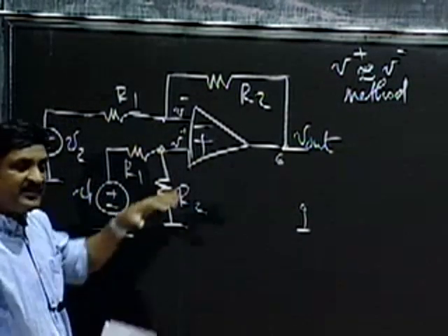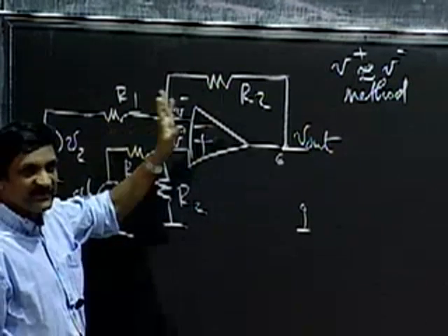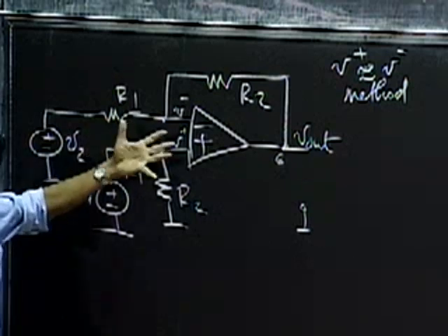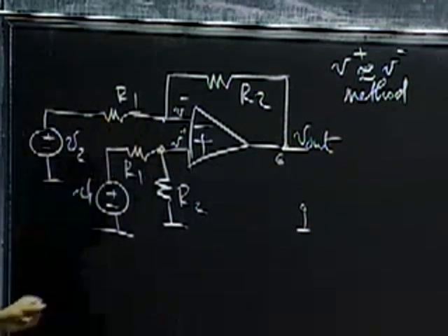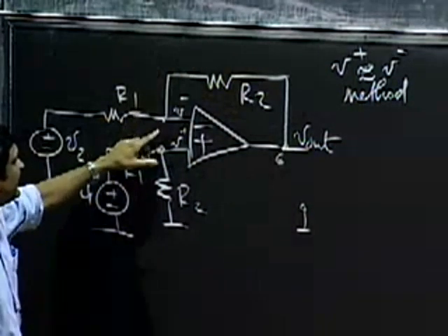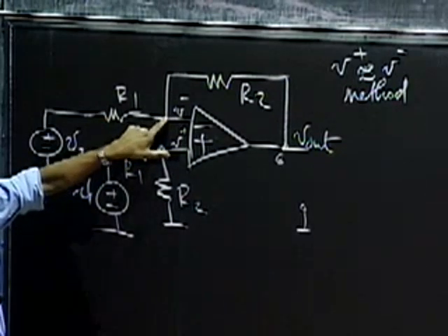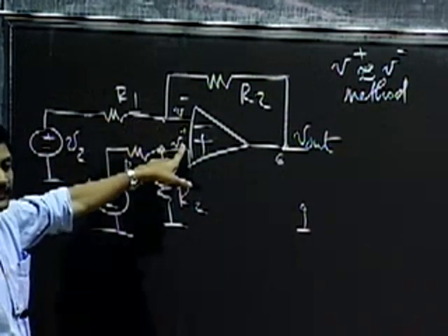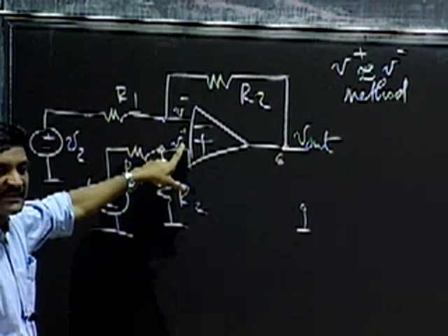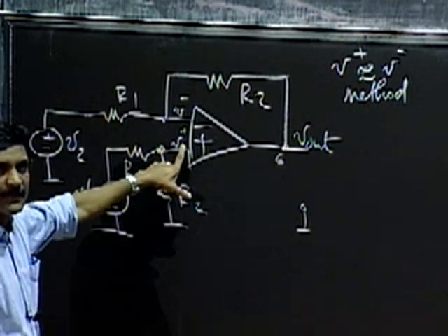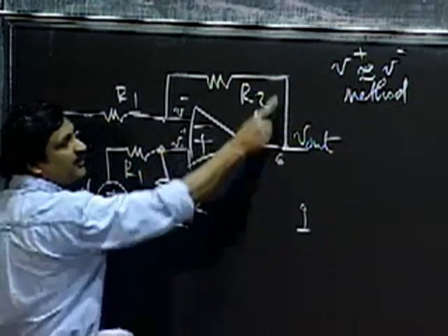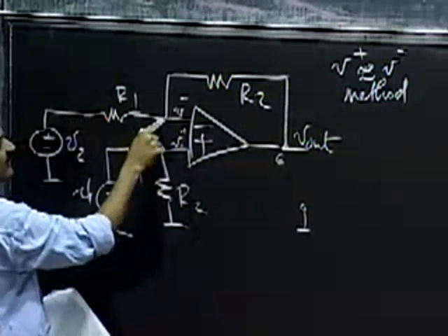So the key thing to observe is under negative feedback, when the op-amp is not in saturation, the property that V plus equals V minus holds. And it's not a magical property. It's simply that when I apply negative feedback, the negative feedback is such that it will force this V minus node here to be at more or less the same voltage as V plus. Remember, when in doubt, simply go back and think about your anti-lock brakes example we did last time.